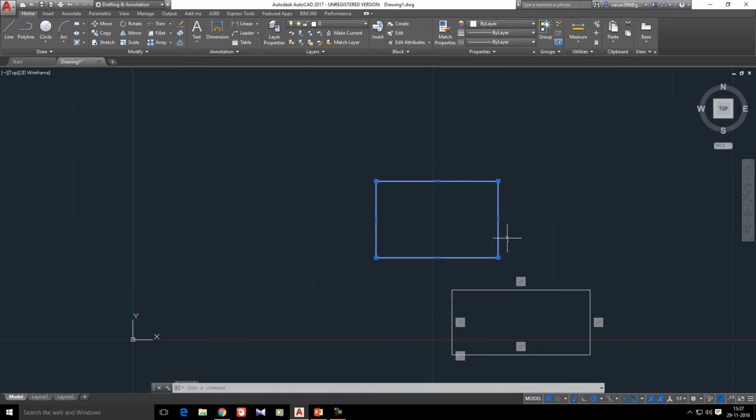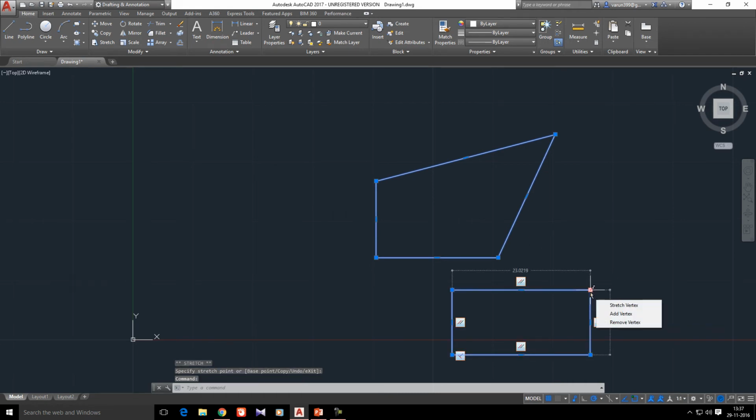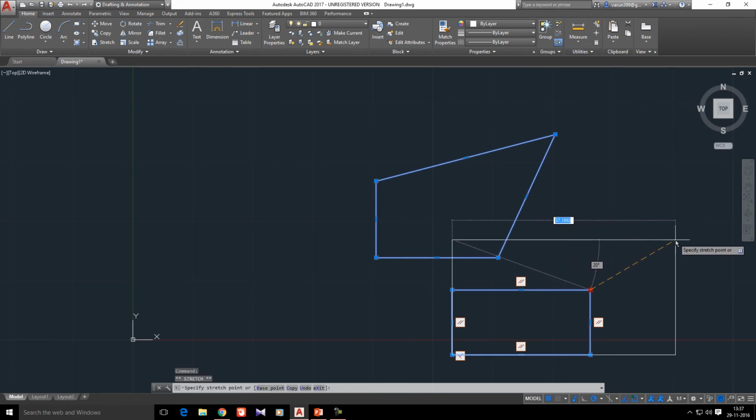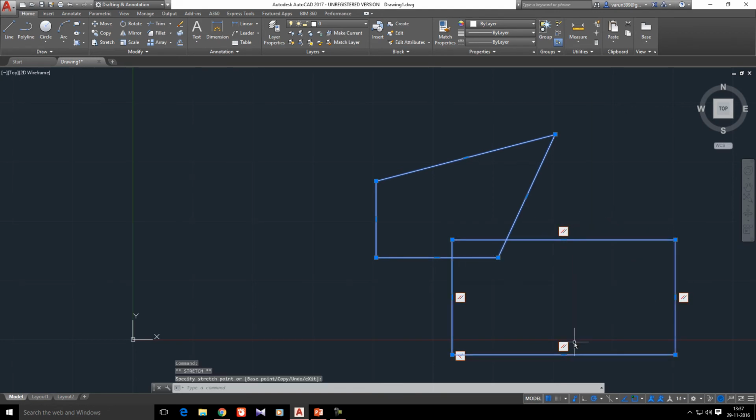Let me give you an example. When you select the first object which we have drawn, select this vertex and extend it, you can see it moves without any constraint. Similarly, when I do the same procedure with this object that was drawn with the Infer icon, we can see that it moves with the constraints available, that is parallel as well as perpendicular. So with this, you can use constraints to draw your objects easily.